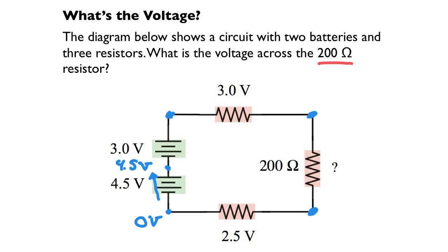One thing you have to know is the direction of the current through the resistors. And in fact, we know the current goes this way, looking at the potential differences across these batteries or power supplies here. They're definitely going to drive current in a clockwise sense. And so for each of the resistors, the positive end of the resistor is where the current comes in. It goes downhill basically in the resistors, and so the other end will be lower. With that in hand, you can look at the potential at different points in the circuit, and therefore you can calculate the potential difference across the resistor. We will do that one in class, but you have everything you need to be able to solve that right now.